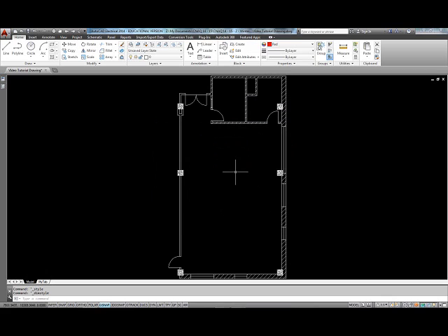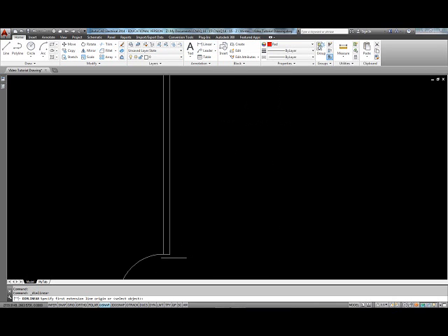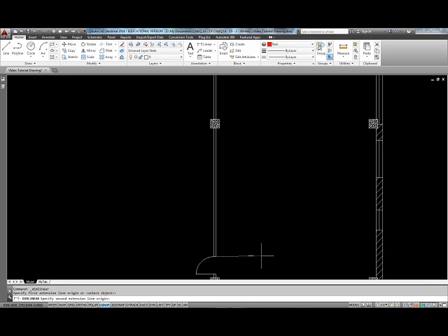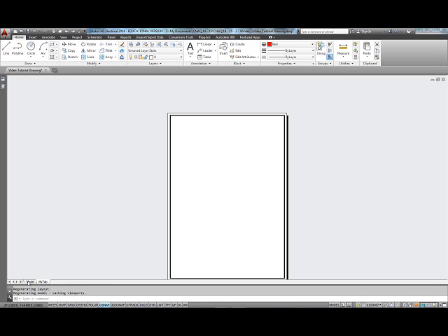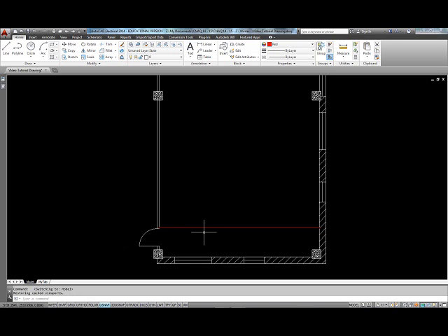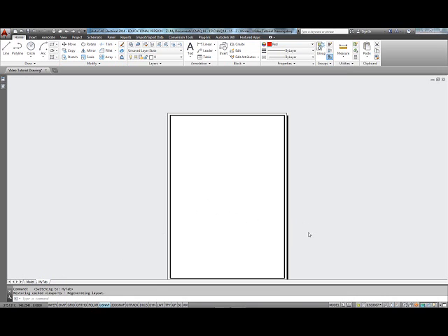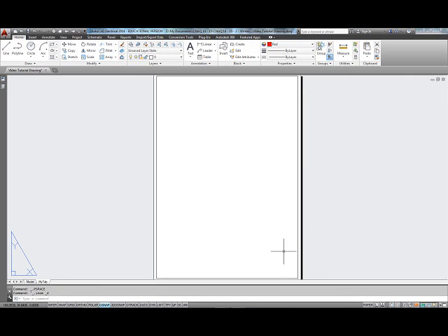Okay, and close. And now let's go linear, pick up from this point to the perpendicular. Why did it not happen? The reason why you don't see it here is because of the same issue that keeps cropping up every time. Before you enter any annotation or text, you must set your annotation scale. And you cannot set your annotation scale until you set your print scale.